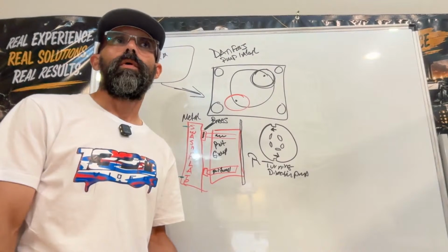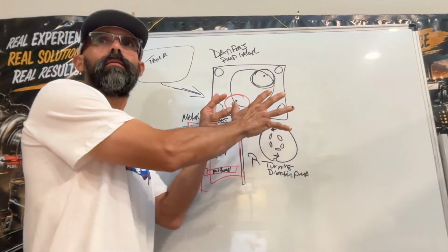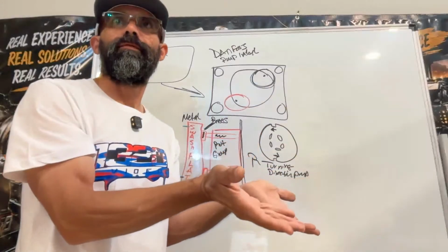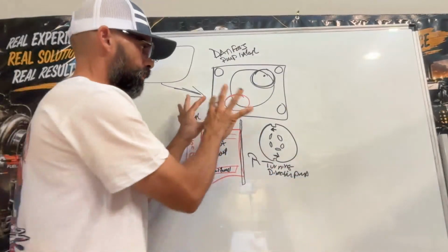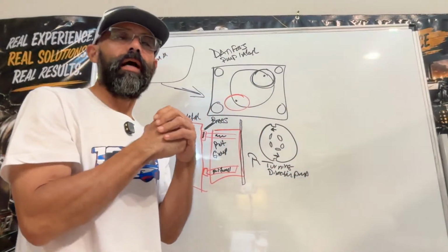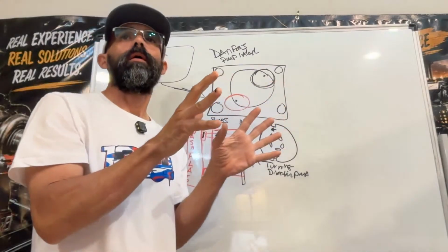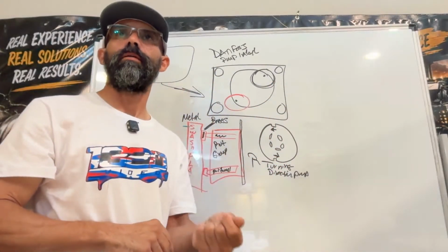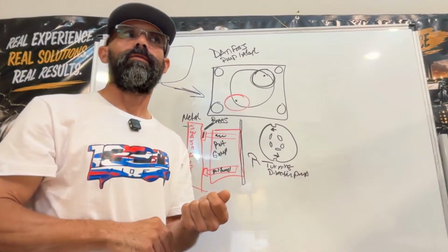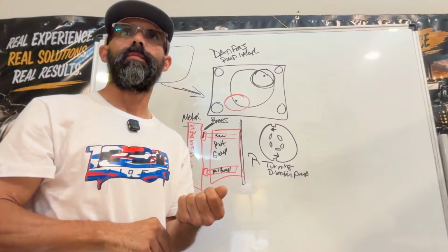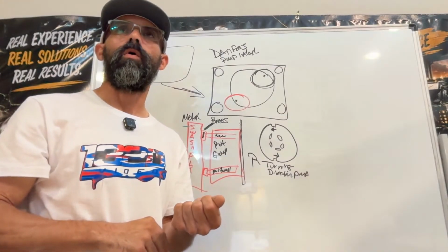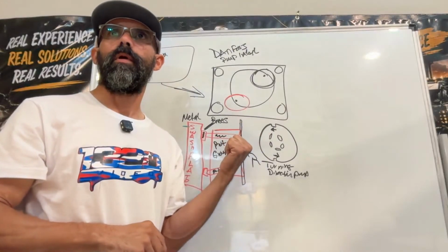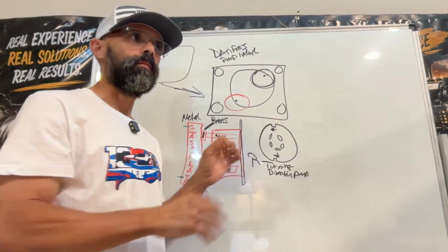So I don't only concentrate on this. I see that the pump failed. Okay, rebuild it. I did my inspection. Oh, okay, wait. It wasn't caused by the pump. There's a piece of steel that either came from a gear pump or came from somewhere, and ended up destroying the pump. So now, before